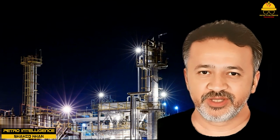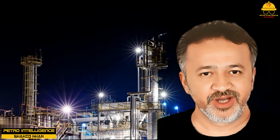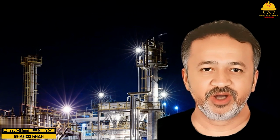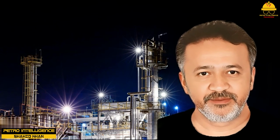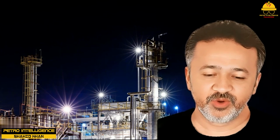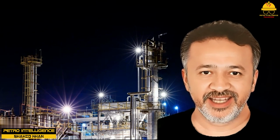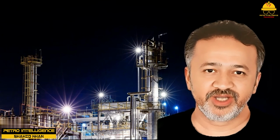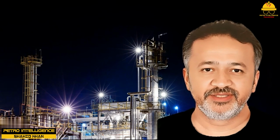Process technicians are responsible for establishing correct flow or feed rates to the reactor, ensuring correct temperature, pressures, and level, monitoring and controlling reaction rates, time, ensuring that specified mixing or agitation is occurring, and monitoring and maintaining auxiliary equipment. Reactors combine raw materials with catalyst, gases, pressure, or heat. A catalyst increases or decreases the rate of a chemical reaction without becoming part of the final product.